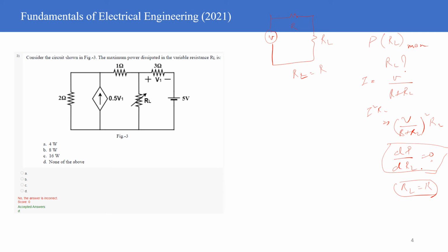I'm hoping this is something you will cover in your undergraduate years, so I'm not going there, but I'm just taking the final result and utilizing it here. The final result says that the power dissipation will be maximum when RL is equal to the overall effective resistance. When you say effective resistance in this particular circuit, you are implying the equivalent Thevenin's resistance, right, Sharad? Right, sir.